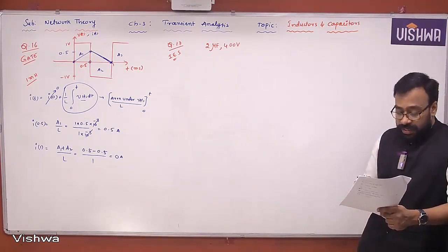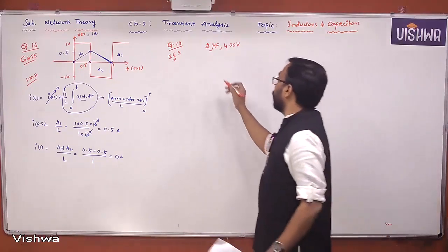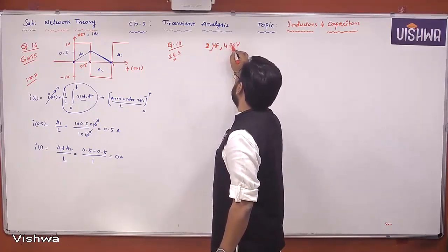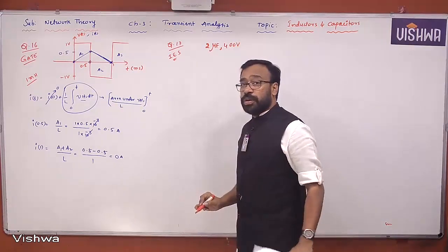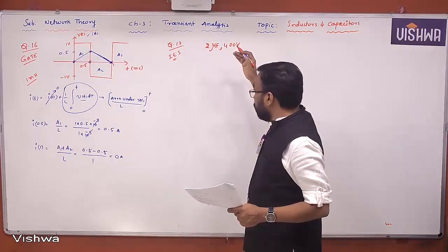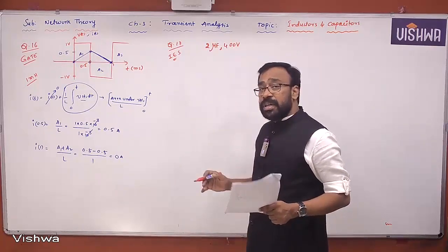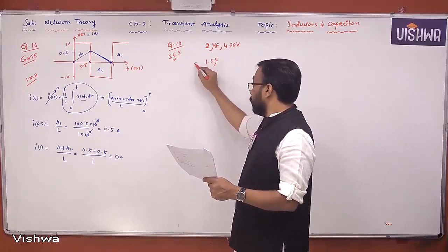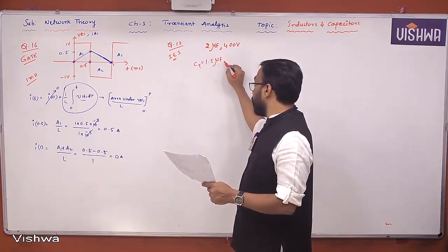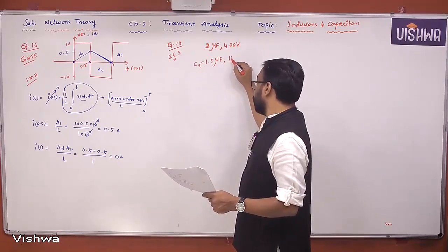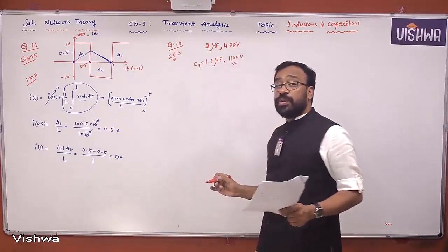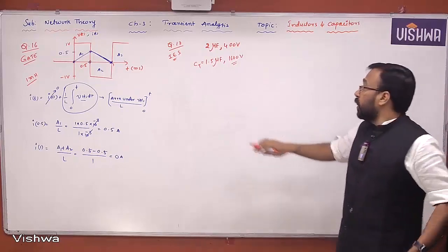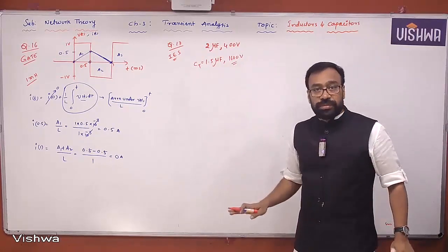Understand? Okay. Here, each capacitor is 2 microfarad, 400 volt. Now you want to take these individual capacitors in a number such that the total capacitance value must be 0.5 microfarad, and the total voltage rating how much? 1600 volt. This is the combination we would like to take. So the combination of different capacitors is required to get 0.5 microfarad, 1600 volts. Understand all of you? Okay.